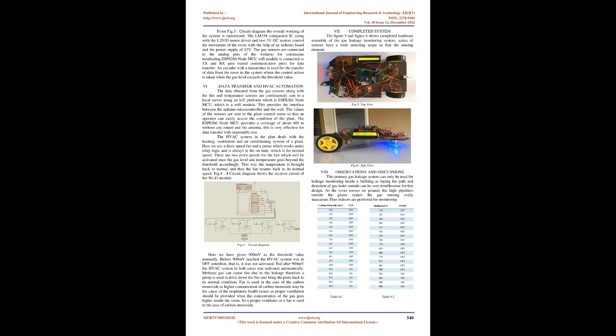These gas sensors are mounted on the top of the rover body and they sense the gas as the rover moves along its prescribed path. The gas concentrations are displayed continuously on the 16*2 display in millivolts, mV, and when a threshold is crossed an alarm is activated. The monitored gas values are also continuously sent to a local server.